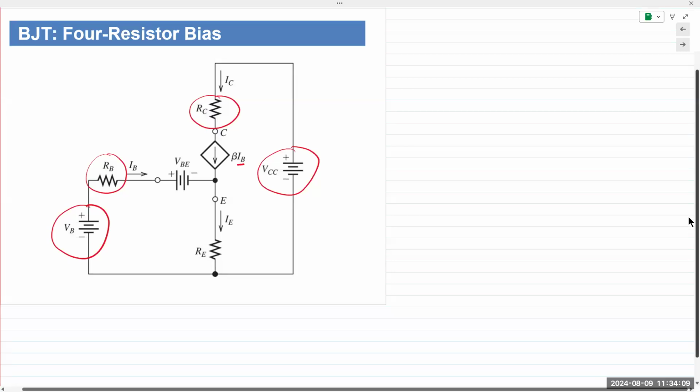Let's say we have a transistor, we connect 4 resistors to it, RC, RE, R1, and R2. If you wish to begin analysis of this, first we determine the Thevenin equivalent circuit for the input side. Then we apply KVL, determine our expressions for VBE and IB, and then we apply KVL on the output side. Okay, so if you look at this model, we can see that there will be voltage drops across these resistors with the polarity as shown.